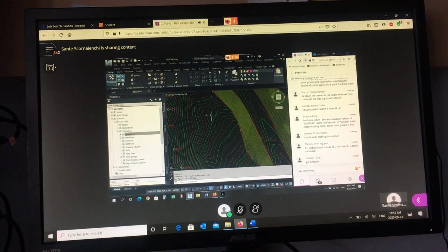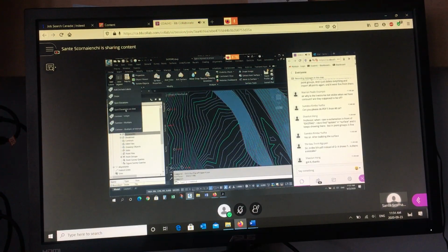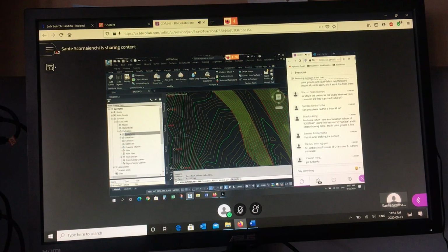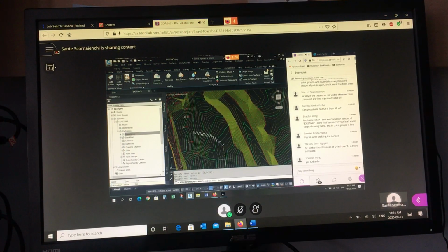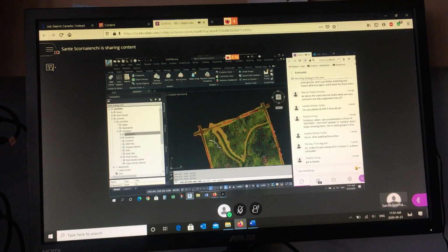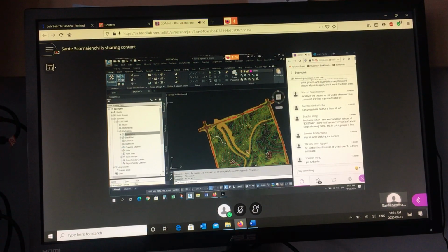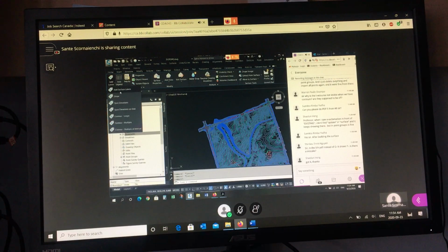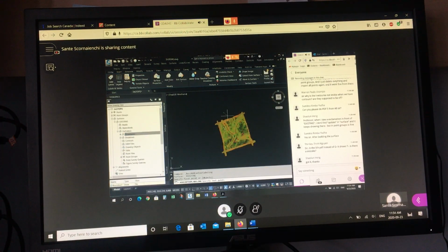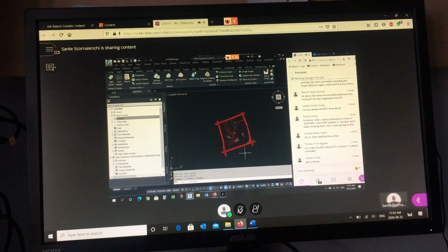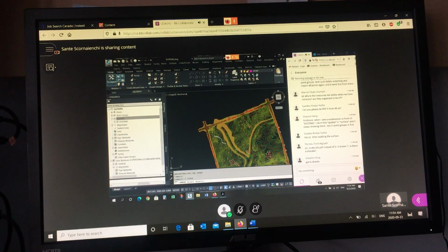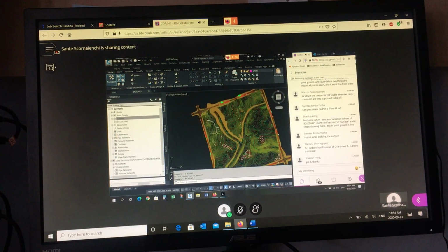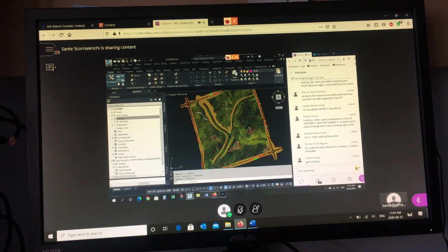When I want to label this, I click on it. I go to add labels, contour multiple, and I draw a line. Again, draw polylines perpendicular to the contours as best you can. Right? Follow the lie of the land. Don't just draw a line through the whole site. Okay? That's not going to give you the presentation you want. You have to make sure you follow the lie of the land. And you want to label areas bound by the water courses. So there's 1, 2, 3, 4 areas that are bound by the water courses.